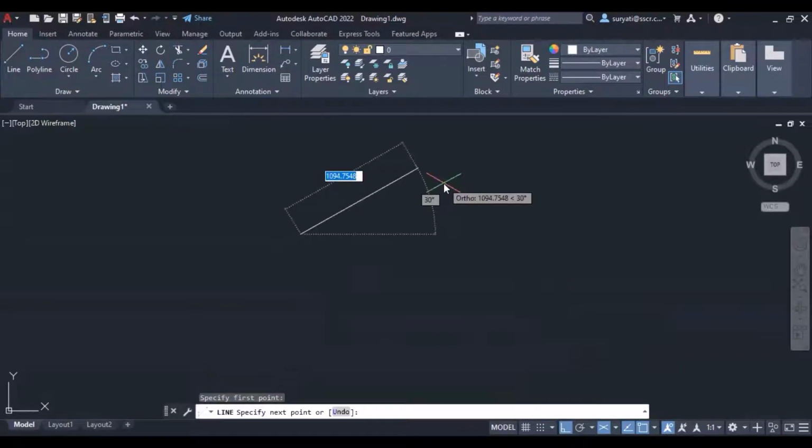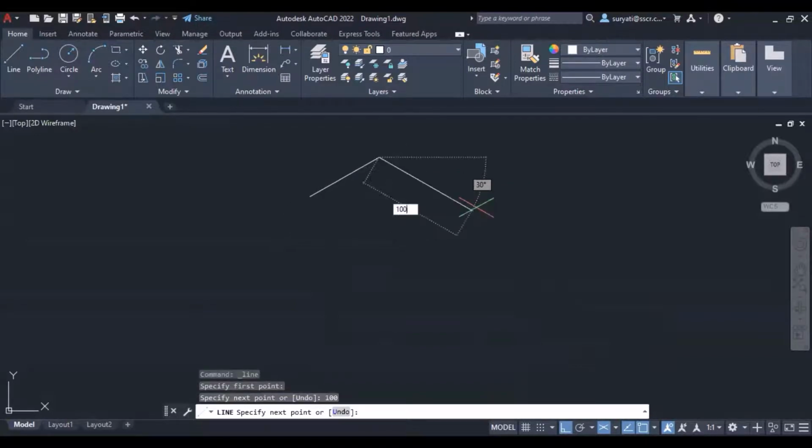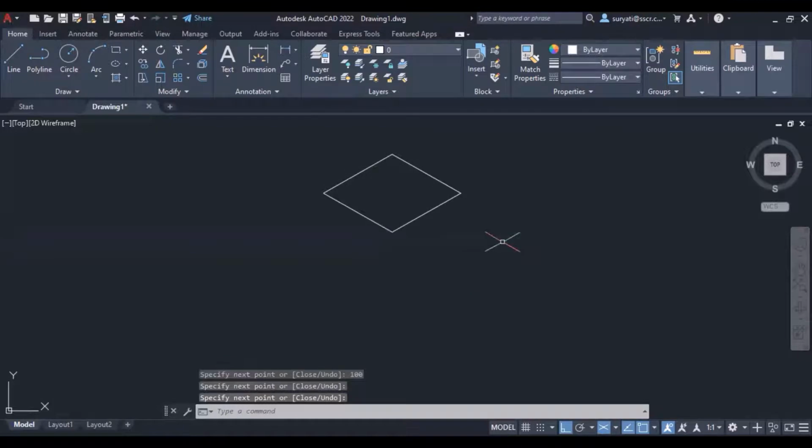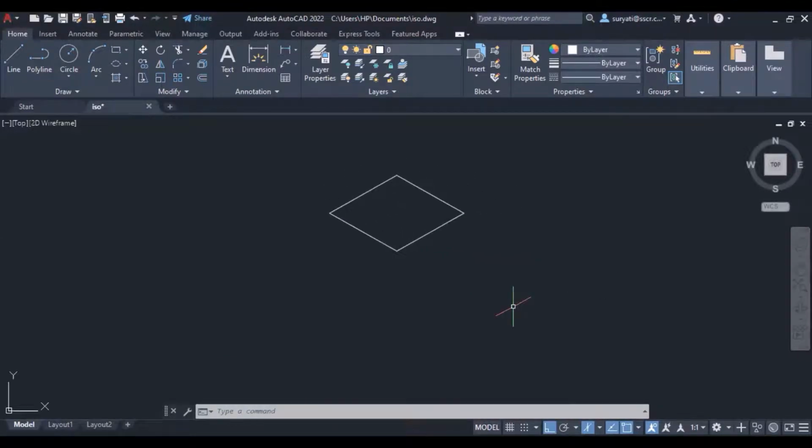And then you can draw following the size. Let's say 100 on each direction. Okay, for example like this. So you drag the cursor 100. Make sure auto is turned on. F8. The keyboard shortcut is F8. Okay, this is a top isoplane. I start with the top isoplane.